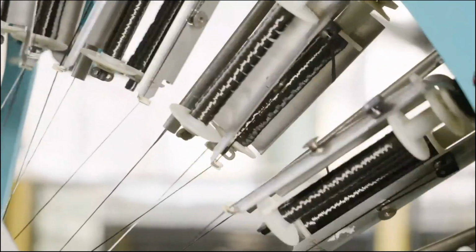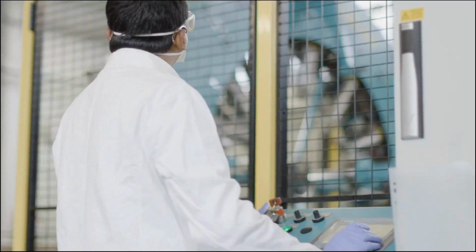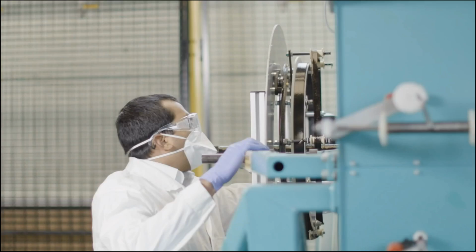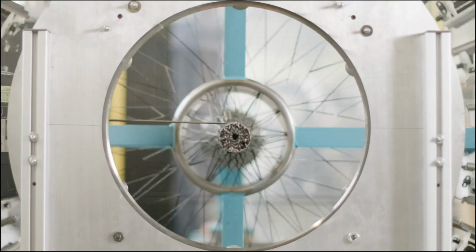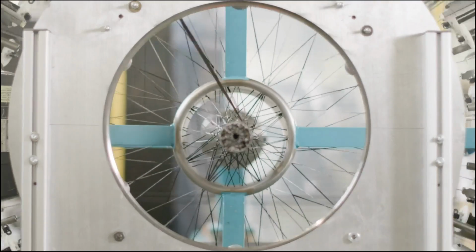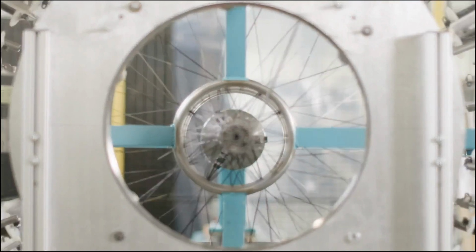For pressurized tubes, braiding can readily incorporate triaxial reinforcement. Combining with the hook reinforcement, we can achieve optimum layups. In Manchester, we developed a complex braid winding machine that significantly expands the process capability to develop quadriaxial layup. This unique machine overcomes the manufacturing challenges of creating optimized fiber architectures.